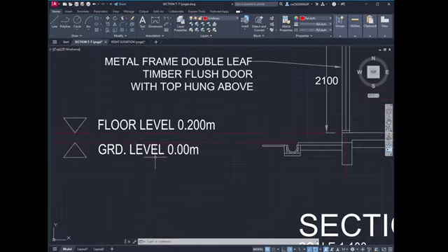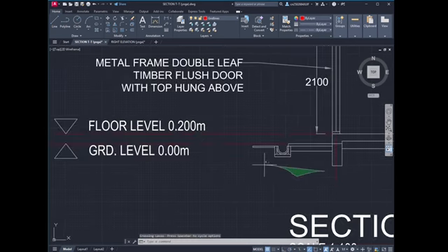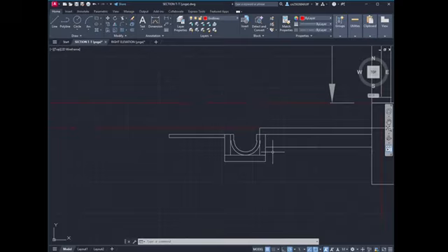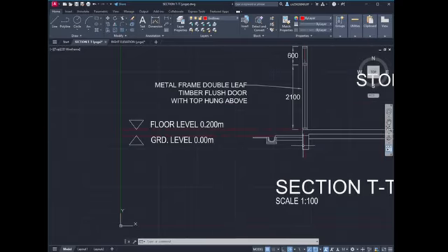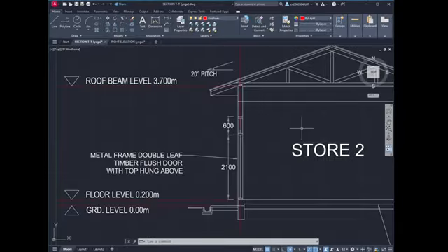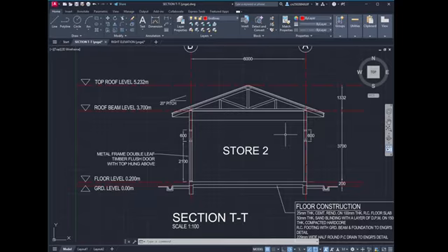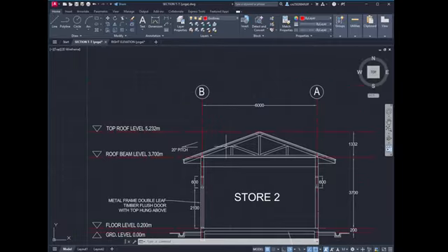And then to draw the drains, I used the PDF provided to get the accurate measurement for all the tiny little drains that I drew. For the text, I used the text command, and for this I used the T-circle command to get the correct circle and object size.